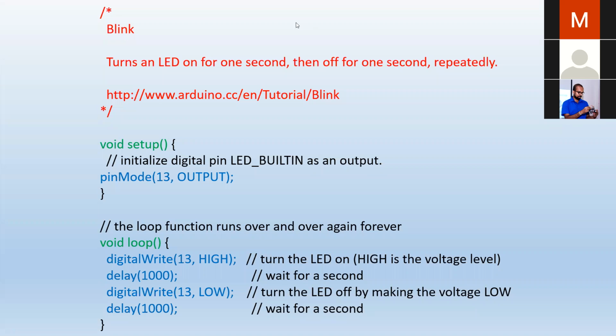There is one other thing I didn't tell you earlier. When you type in a delay in Arduino code, the Arduino board is going to freeze for 1 second, right? It is not going to do anything else in this 1 second delay. That is why, when you get more advanced with the Arduino, there is a thing you do. It is called ditch the delay. Ditch the delay means you don't use delay when you get more advanced with the Arduino environment, right? The delay is going to freeze the Arduino code or the entire MCU, the microcontroller.